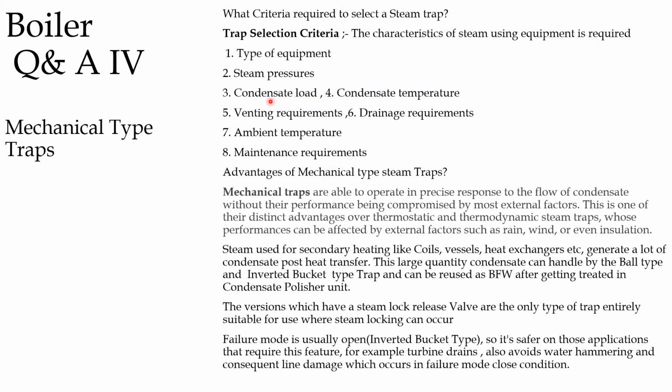Condensate load depends on how the condensate is produced. Condensate temperature is also required. Venting requirement, drainage requirement, ambient temperature required, whether the trap will be affected by freezing up, and the maintenance requirements. Advantages of mechanical steam traps. Mechanical traps are able to operate in precise response to the flow of condensate without their performance being compromised by most external factors. This is one of their distinct advantages over thermostatic and thermodynamic steam traps, whose performance can be affected by external factors such as rain, wind, or even insulation.